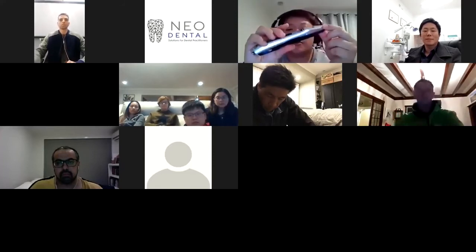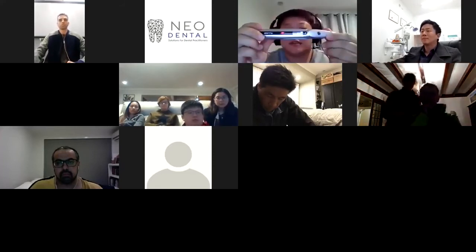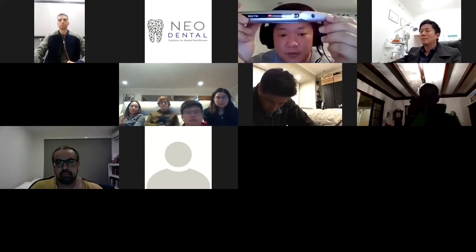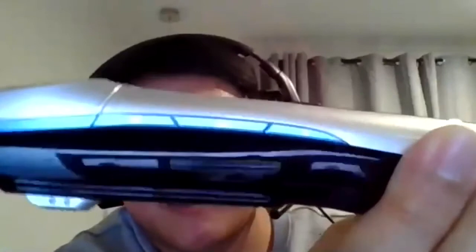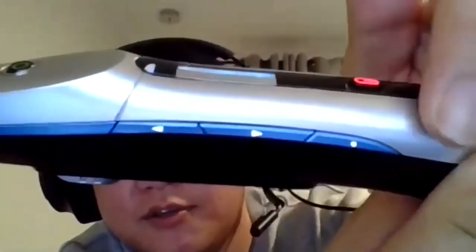When you turn on your unit, it has a nice welcome sign. It's not very great trying to show this on a webinar, but when you turn it on, you'll get a prompt for a password. I've been told that a lot of people get confused about it, but it's just a safety mechanism for most lasers, to prevent kids and people who shouldn't be playing with it. The code is actually just set as 0000. So you just need to push the button that's got the dot on the back. This button here, push that 4 times, and that'll log you into the laser.